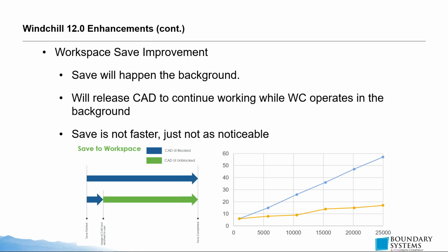If you're doing a save and upload or a complete check-in, your Creo session will only stop working while it's going from your Creo session to the workspace. Once it's in the workspace and it's beginning to upload the information into Windchill or check in the information into Windchill, your Creo session will become available. So all of the interaction with Windchill happens in the background.